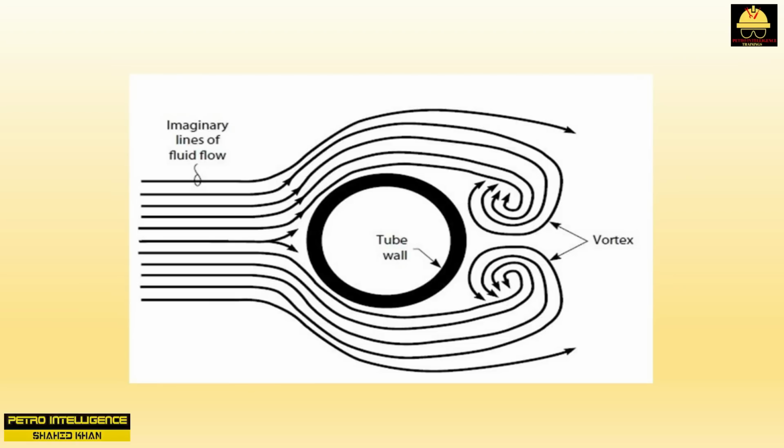For example, I recall a -40 degrees Fahrenheit day. The air is quite still, and I am comfortable. Suddenly the wind comes up. The rate of sensible heat transfer from my body to the ambient air increases tenfold. Why does this happen? Our bodies are always surrounded by a thin layer or film of stagnant air. This film is like a layer of insulation. It retards heat transfer between our skin and any surrounding fluid. Movement of the fluid causes turbulence. The turbulence disturbs the film and reduces the film's resistance to heat transfer.